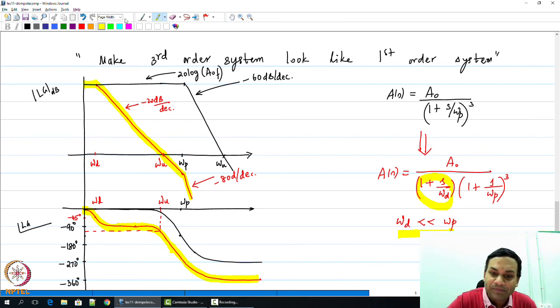Now, most importantly, I am going to show when the phase crosses 180 degrees. That happens at this point, and as you can see, when the phase crosses 180 degrees, the magnitude of the loop gain has already become smaller than 1. Alternatively, you can see that when the loop gain has actually hit 0 dB or a value of 1, the phase has not hit minus 180 degrees. So clearly the system is technically stable as I have drawn it.